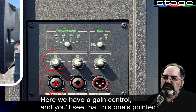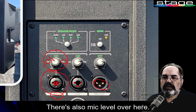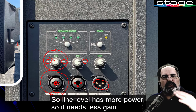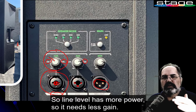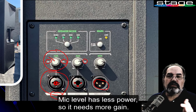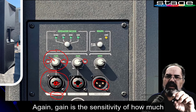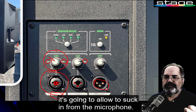Here we have a gain control, and you'll see that this one's pointed a little bit more off to the line area, for line level. There's also mic level over here. This one's pointed more towards mic level. Line level has more power, so it needs less gain. Mic level has less power, so it needs more gain. Again, gain is the sensitivity of how much it's going to allow to suck in from the microphone.